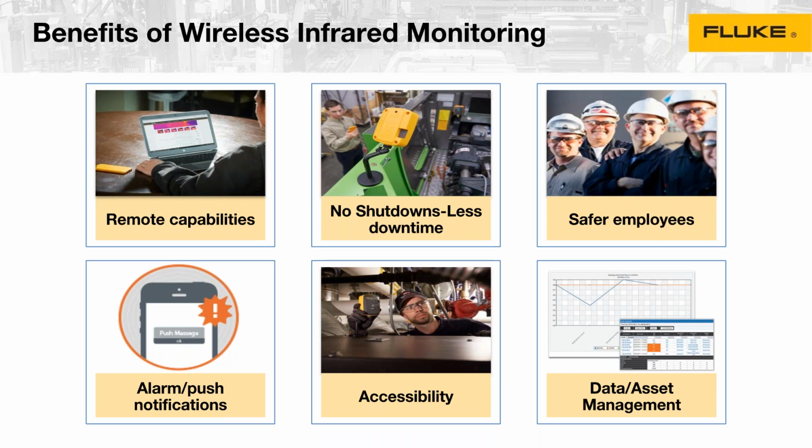It does not have to be in a particular location. Sometimes it could be in a place where it's really hard to reach, and you want to mount this. So you may not be able to, or you could not, if you had a handheld infrared camera by itself, stay there for much longer because either it's too cold, too hot, too dangerous, or there's just rotating equipment. By leaving a sensor there and stepping away from the application, you still get the picture, but without being in